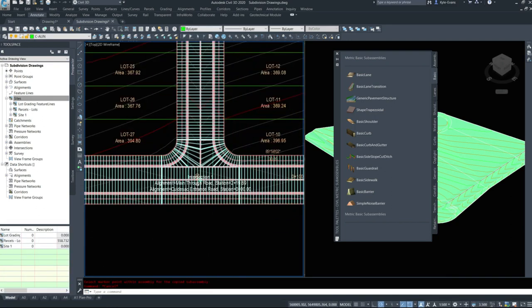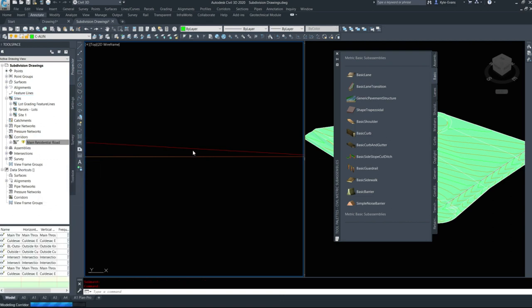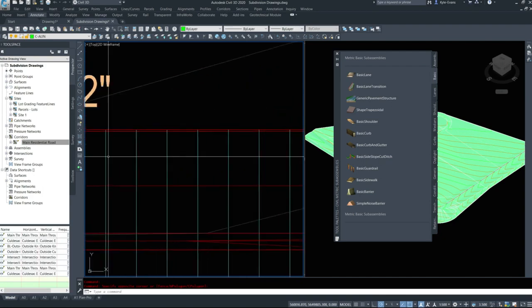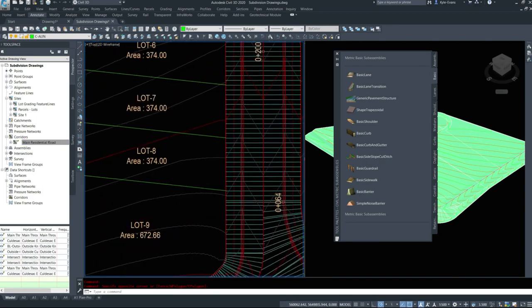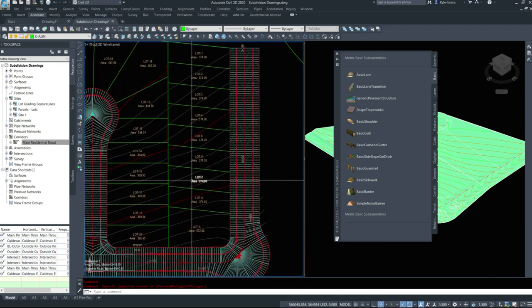So going over to my corridor, I'm going to zoom in on the edge. And again, this is not that large, it's only 0.05. But when I rebuild this, we should see an additional red line pop out, maybe around where my mouse is here. And give that a second to rebuild. And there it has. So now, if we look at where a feature line is connected, we can guarantee that the feature line is covering the actual surface, and if we update something, it will rebuild.